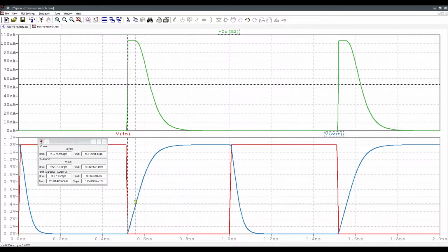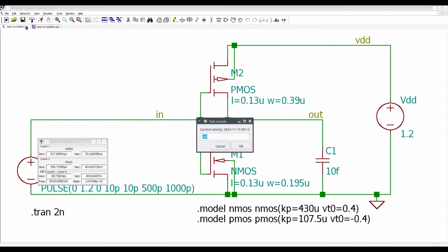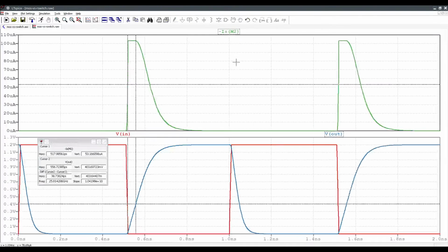And we can tell that in a lot of ways. One, by looking at this, the gate to drain voltage is large enough that we do have a channel on the drain side. I can also tell in the drain current for the MOSFET that it is no longer constant and it decreases. Remember, it's a parabola, and as we get down here, our curves look exponential because they're going to converge to exponential as we go down. Okay, so let's delete this one.